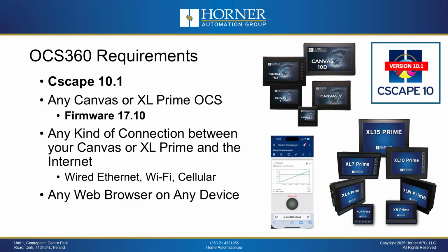Now let's talk about the requirements. Because this is new, you will need Cscape 10.1. You are going to need either a Canvas or Prime controller, and that controller is going to need a firmware version of 17.10 or later.